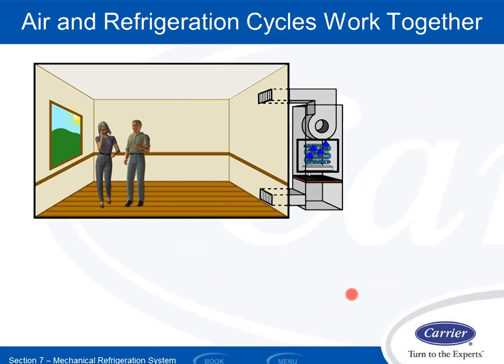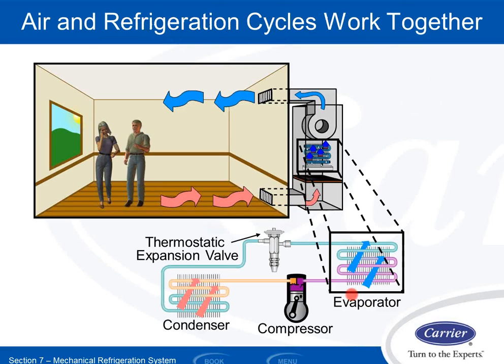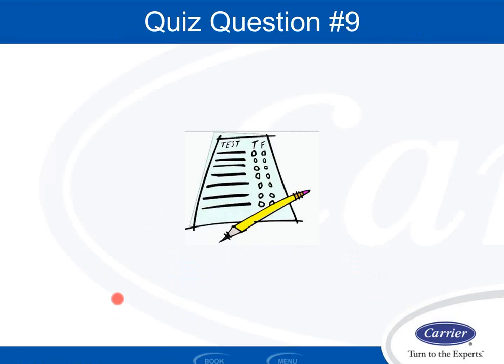Now all I'm gonna do is take that cycle and stick one end of it into my airstream. That's the evaporator side. The condenser side, I'm gonna stick into a piece of equipment outside and blow a fan across it as well. I blow fans across both the evaporator and condenser coil to speed up the heat transfer process. Otherwise, this would take forever, and I would need crazy massive size heat exchangers.